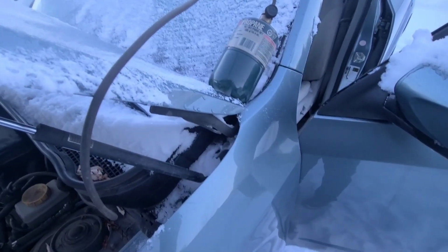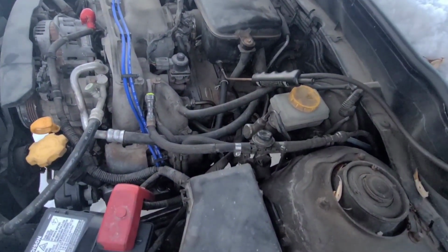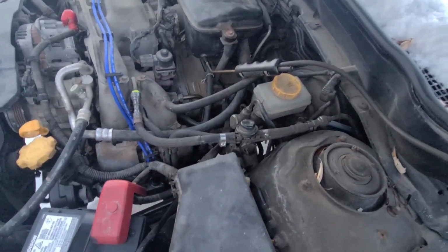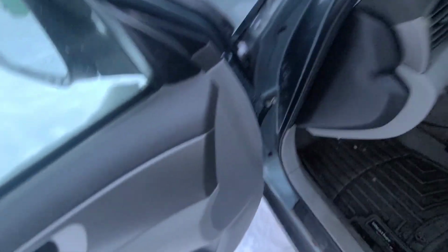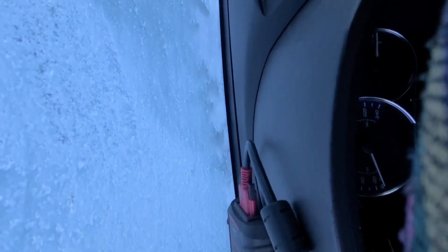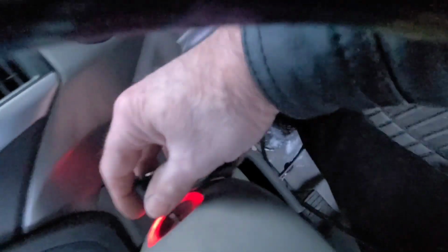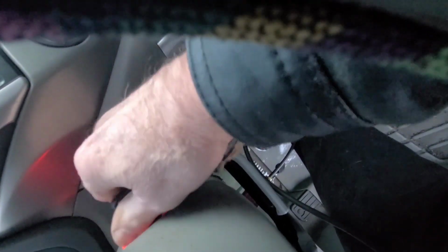So I've got a propane bottle here with a small propane heating tip plumbed into the PCV fresh air intake into the air induction system, and I'm going to try cranking it and adding propane while it's cranking. Now I can't videotape this. Let's try it like this. Here we go.